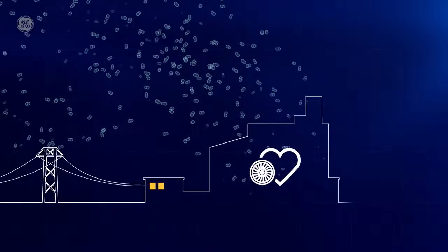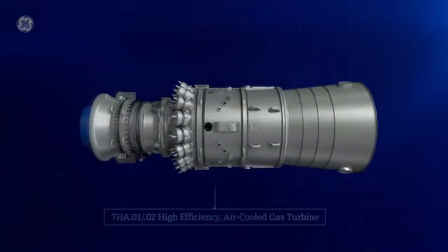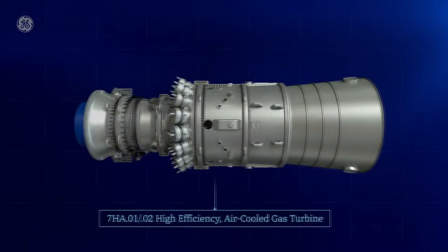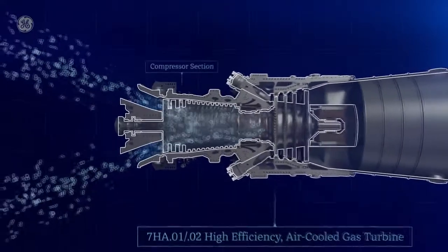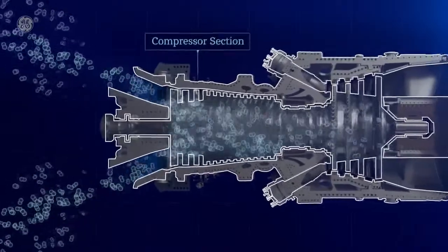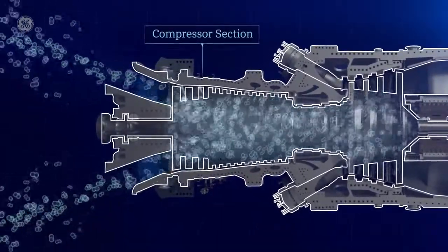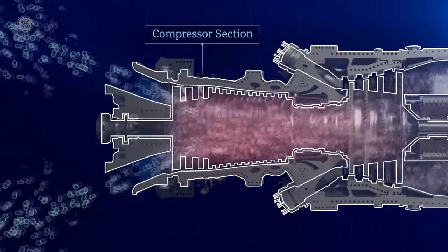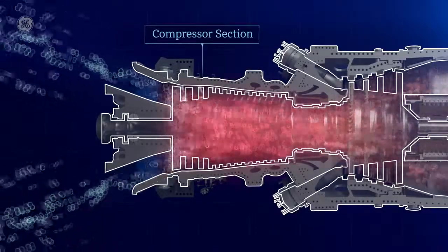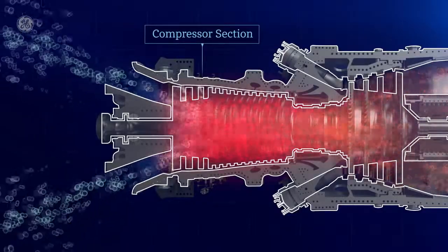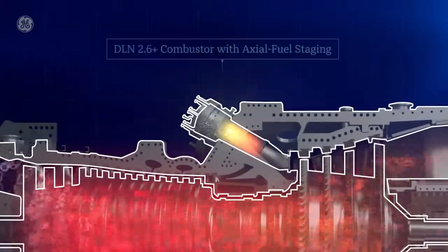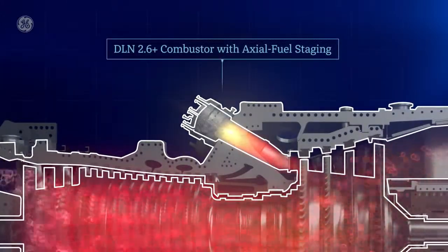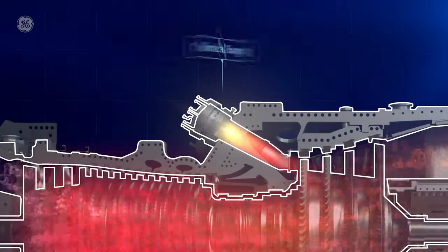And you know that in the gas turbine, the air will be compressed and squeezed in the compressor section. As the air is compressed very high, it will be hotter. The temperature will be increased and also the pressure will be increased. And besides, the fuel will be injected into the combustor to produce hot compressed air, and at the same time it will be burned, and it uses the chemical energy.